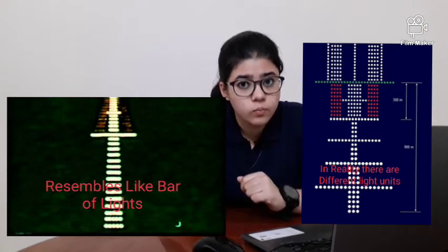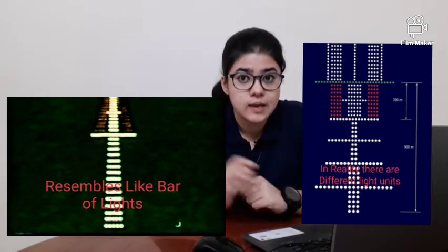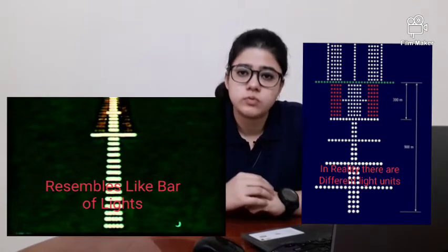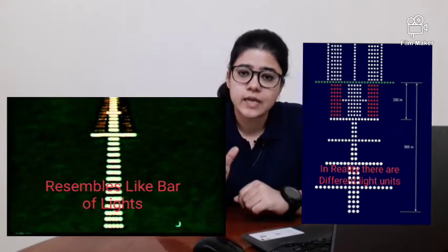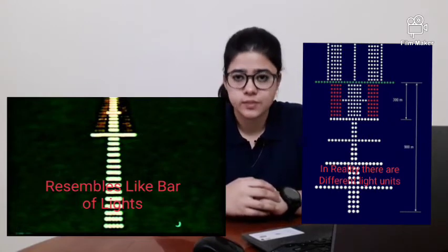Next, we'll be talking about barrettes. Barrettes are a system of 3 or more aeronautical ground lights placed so close to each other in a transverse line such that they appear as a short bar when seen from a distance. Next, we will be talking about balked landing. It is a landing maneuver which is abandoned when the aircraft descends below the decision height or obstacle clearance altitude.